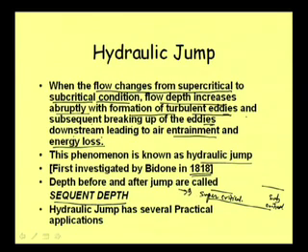Discharge is the same, Q discharge is coming. For the same discharge, we have supercritical flow here, subcritical flow here. Then in the flow from here to here, the critical depth may be somewhere here. This is say Yc, the critical depth line. Then from this point to that point, water will be moving, creating a lot of turbulence. A lot of eddy formation will be there at the beginning, then smaller eddies, and ultimately it will meet this depth, and this phenomenon is called hydraulic jump. The depth upstream, this one, is say Y1, and the depth downstream is say Y2. Sometimes people write y dash and y double dash also. Anyway, this Y1 and Y2 are called sequent depths of hydraulic jump.